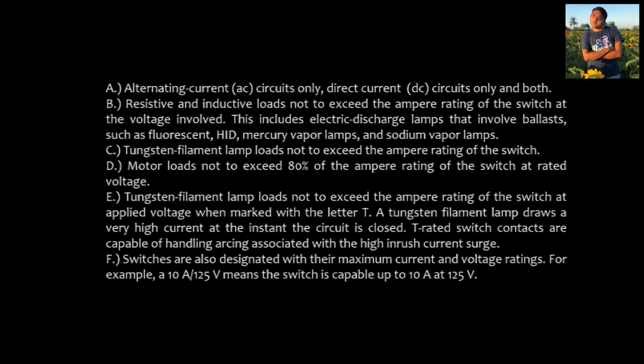F. Switches are also designated with their maximum current and voltage rating. For example, a 10 ampere over 125 volt means the switch is capable up to 10 amperes at 125 volts.